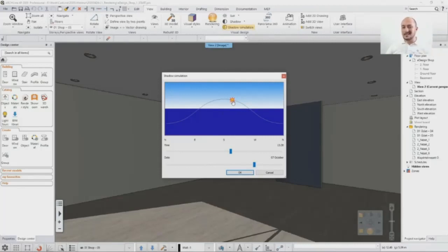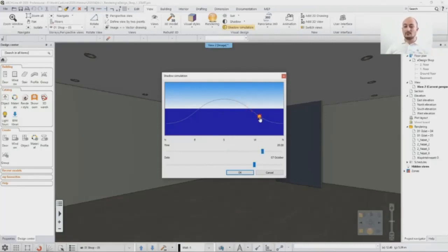If you would like to create a night scenery, you need to move the sun below the horizon, either by using this or by using the time slider. So in that case, you will have a night scene. So I think I will just set up a different time somewhere around summer. While we are on this northern part of the globe, it means that we will have a high-pitched version of the sun, the sun angle will be quite high. So I'm willing to use that because the sunlight itself is not coming into the model too much.